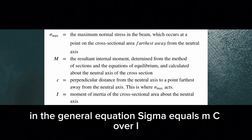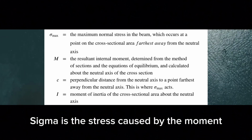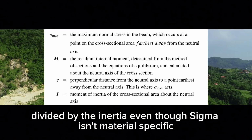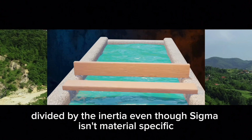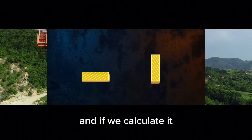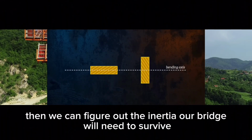In the general equation, sigma equals Mc over I. Sigma is the stress caused by the moment times the distance from the neutral axis divided by the inertia. Even though sigma isn't material specific, the modulus of rupture is, and if we calculate it, then we can figure out the inertia our bridge will need to survive.